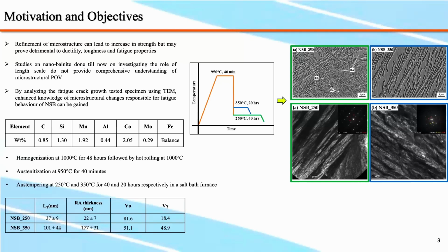There are two primary microstructural constituents: bainitic ferrite, and another known as retained austenite. Once we examine the microstructure using a scanning electron microscope, by etching the sample using a 2 weight % nital solution, we observe that most of the bainitic ferrite gets etched away, and what remains is the two different morphologies of retained austenite.